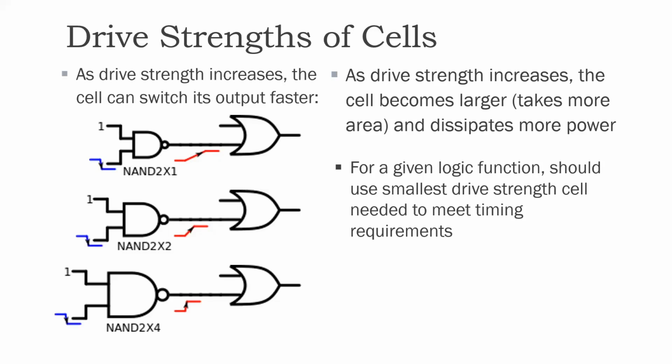Also, without a variety of drive strengths, the implementation of the logic can be very non-optimal. The area of the design may be too big, or it may consume too much power if you don't have different drive strength cells in the library.